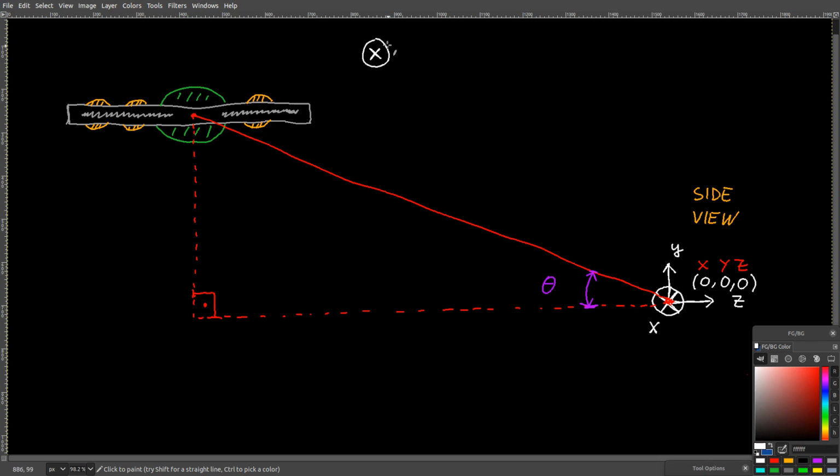When representing axes in a 3D space on a 2D plane, the convention is that if the axis arrow points away from you, then it's a cross. It's like looking at an arrow from behind. However, if the axis arrow points towards you, then you have a point and a circle around it, as if you were looking at an arrow's tip when you stand in front of it.